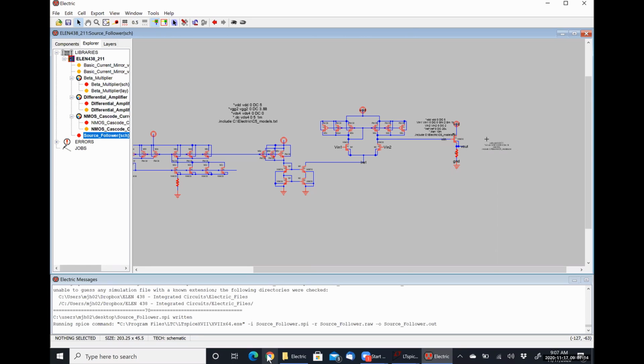Gotcha. In the 120 class, if they run their little SparkFun display at too high of a brightness, it'll do that exact thing. So it's overheating your voltage regulator, because there's a reason that microcontroller is $20. Gotcha. Do you think if I throw a capacitor across the power rails that it would maybe help that, or should I just buy a bigger power supply?